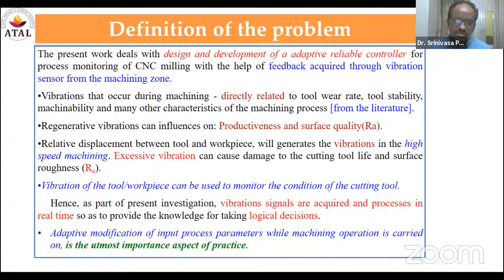If you want to define a relationship between the vibration parameter and the surface roughness, based on the mathematical equations, sometimes it is useful to use velocity, sometimes acceleration, sometimes displacement, depending upon the mathematical relationship. It is up to us to decide which one matches the left hand side with the right hand side with respect to units. Then consider that particular parameter.